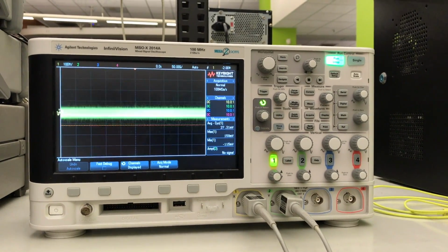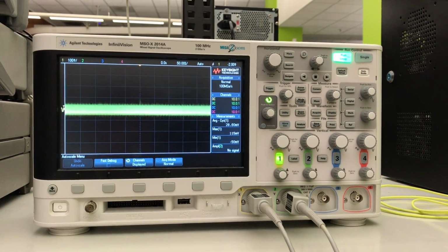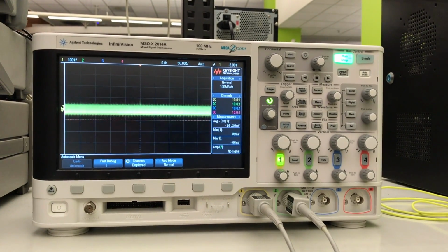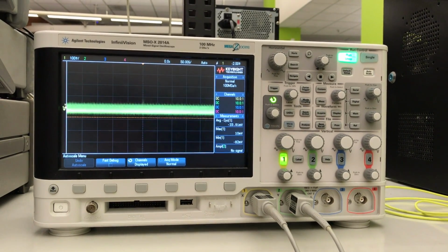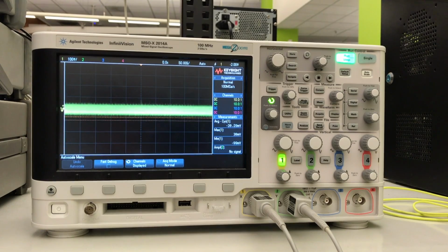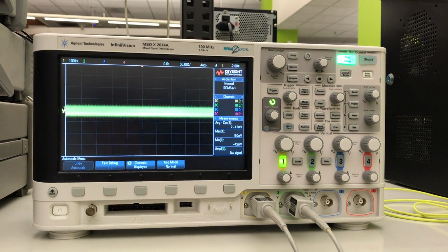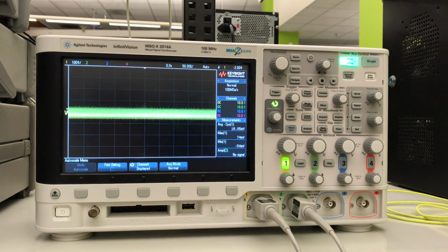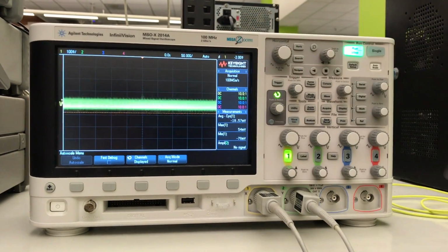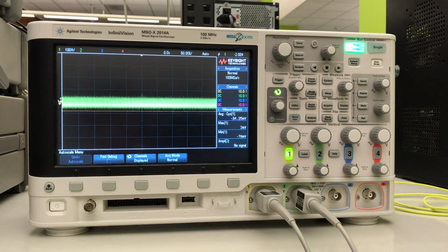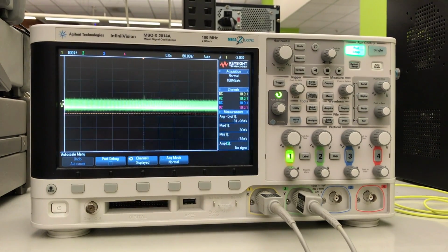Now we will look at how we can use the oscilloscope to actually see the signals within the circuit. There are two different axes on the oscilloscope screen itself. In the horizontal direction, we are looking at time steps. So each little square of that grid corresponds to a unit of time. You can find that time measurement right here up at the top of the screen. Right now, we are seeing 50 microseconds per little square of the oscilloscope screen.